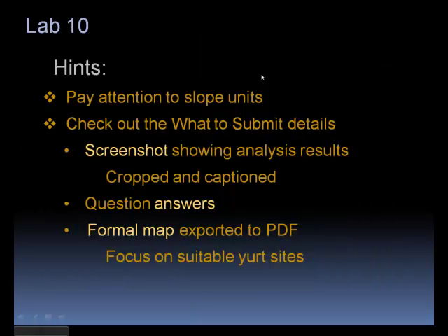Okay, so again, make sure when you run your slope that you're calculating it in percent. I don't want to have to tell you after the fact and have you go back and retrace your steps and start half your analysis over again. So save yourself some time and make sure that you run your slope in percent rise.